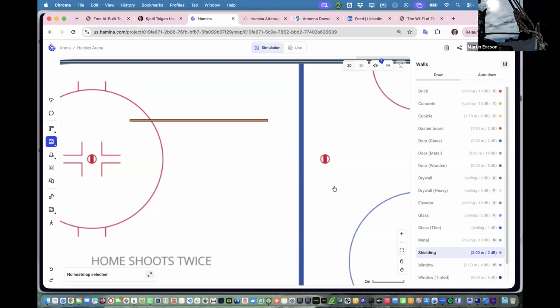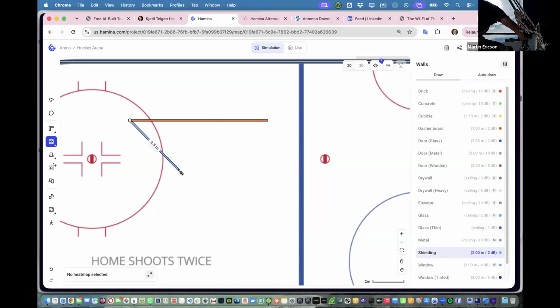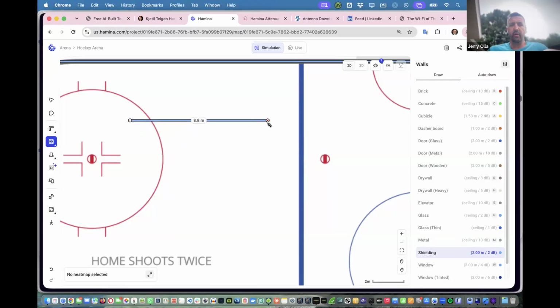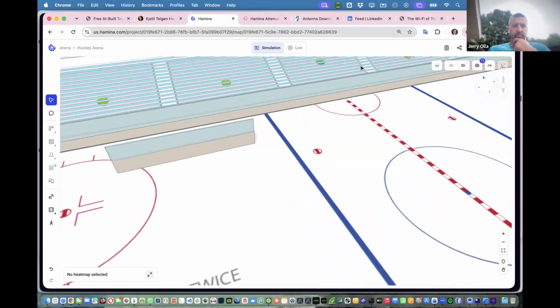I would first not hold it when you do the first click, because then it still snaps to that position. But now hold down shift before you put the last click, and that should keep the underlying material. So I'm holding shift and now left click. Yep. And now that should do it.